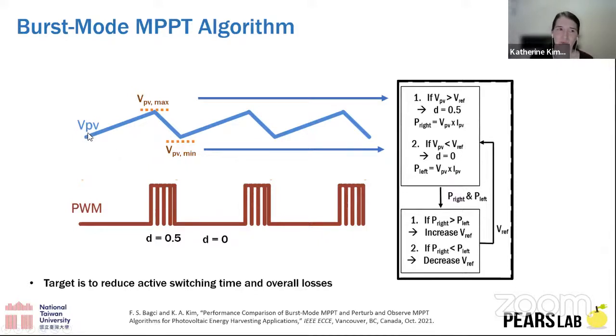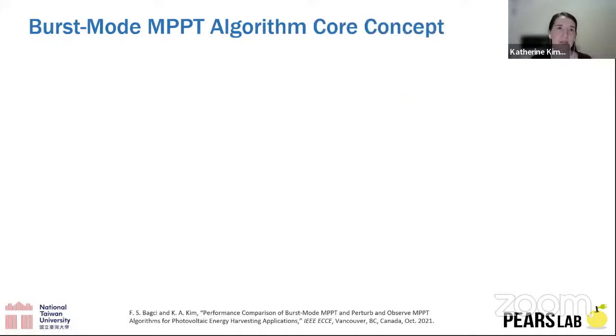The idea is that you let the converter naturally go to some state, then you turn the converter on, burst, and that will affect it, and then it will relax again, and we turn it on whenever it gets to a certain point. So we use a hysteretic type of controller and then burst it on and off to control it.